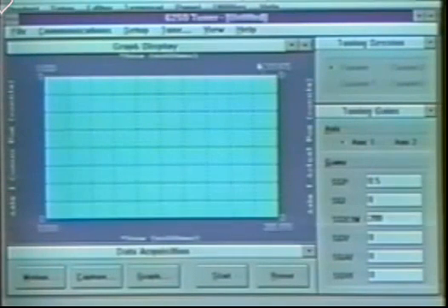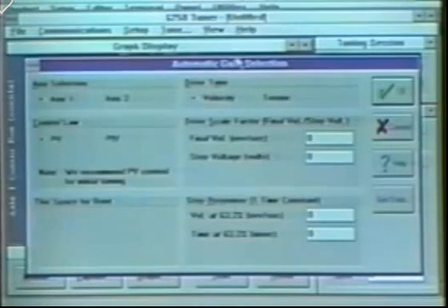The next thing on the menu is Tune. This is an automatic gain selection. A customer can use this feature to have the Servo Tuner calculate theoretical gain values based on the motor load data. These values give a great starting point, but are typically tuned way too tightly, and the gains often need to be reduced to satisfy the application.